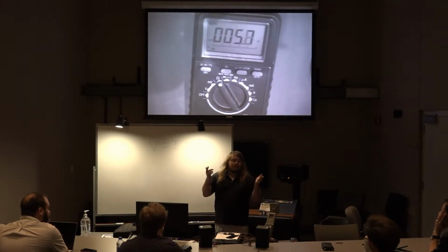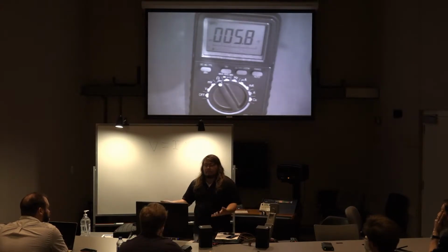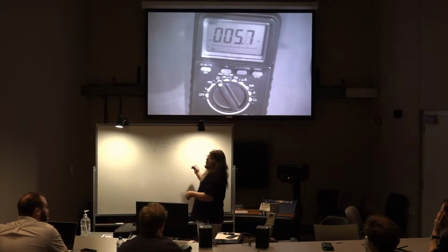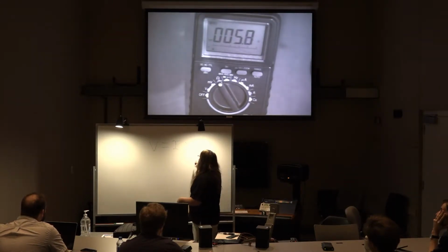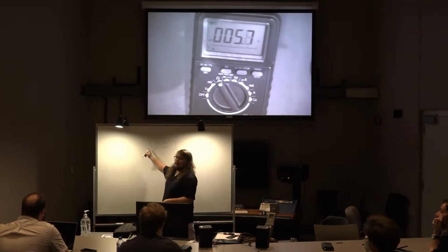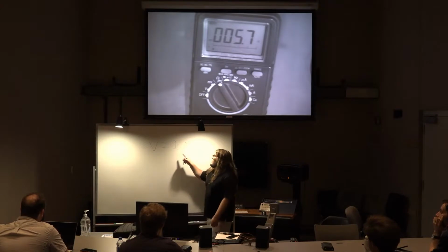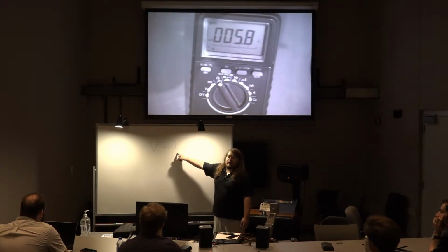With 2 speakers hooked up in parallel, we have 3. Okay, so what happened to the resistance? It went down, correct? Right. And the voltage did what? Stayed the same. Okay, so if the voltage stayed the same and this went down, what happens to the current?